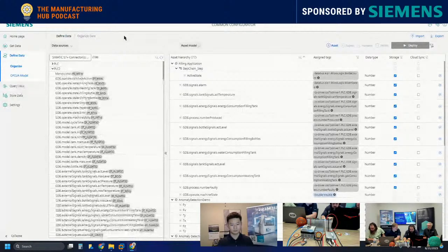So a couple of questions I think came in that we should probably address. Number one, does the write data to PLC feature only work on the virtual PLC app, or is it also capable of writing data to the physical PLC connected on the floor? And again, my first take is I think those are disjointed, right? It has nothing to do with the virtual PLC. It is a feature inside of IIH that you can write back to the PLC, regardless of the device, right? The two concepts are separate.